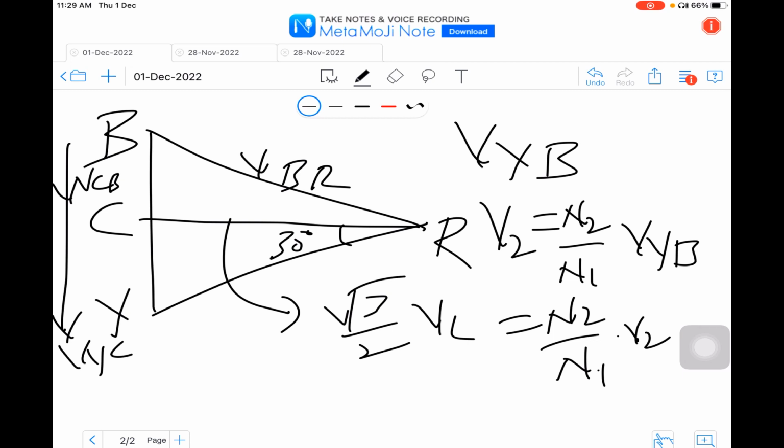From the phasor diagram, we can observe the line voltages of the three-phase system, VRY, VYB and VBR, are balanced, and they are shown on the phasor diagram as a closed equilateral triangle. The voltages across the two halves of the center tapped primary of the main transformer, VCB and VYC, are equal, and they are in phase with VYB.